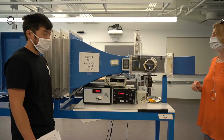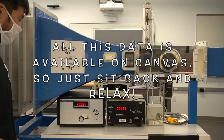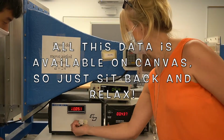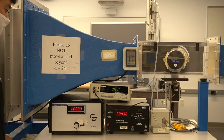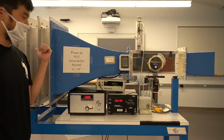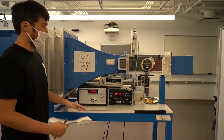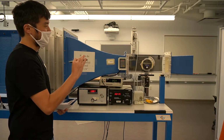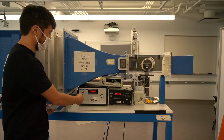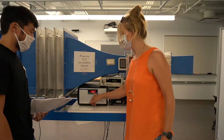All right, so we've moved our airfoil up to 3 degrees, and our lift voltage is now 0.052, and our drag is negative 0.006. We see that there's a negative value in front of the drag. Obviously, we're not creating negative drag, which is thrust in this case. That's just a matter of direction. So with our airfoil system, positive drag is defined as thrust in this case, and the negative drag is actual drag, so that's why there's a negative sign in front of the drag. So when you're writing down your values here, you're just going to write down 0.006.